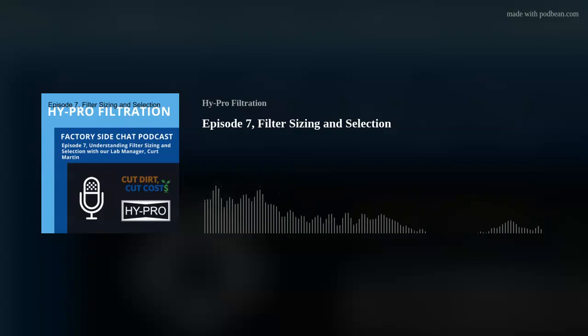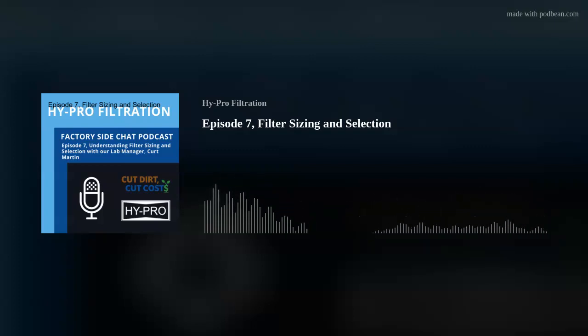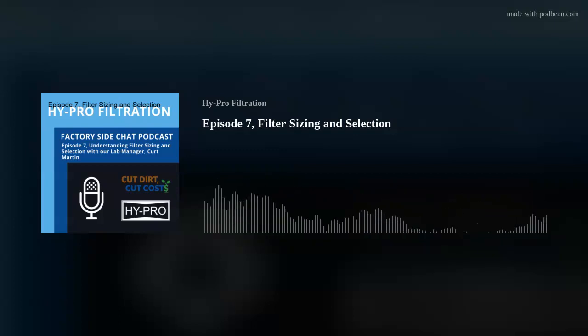Yeah, that's really good information. So basically what we're trying to say here is filter sizing and selection is not an exact science. We look at each application individually, and then we help them determine what's best for their situation. As far as turns a day, let's say a customer asks you to size a new FSL skid, some type of fixed skid on the system. Turns a day, I typically would say a minimum of 8 to maybe double that if you're in a very difficult situation. What are some of the things you like to ask them when it comes to environmental conditions to help you determine the flow rate?